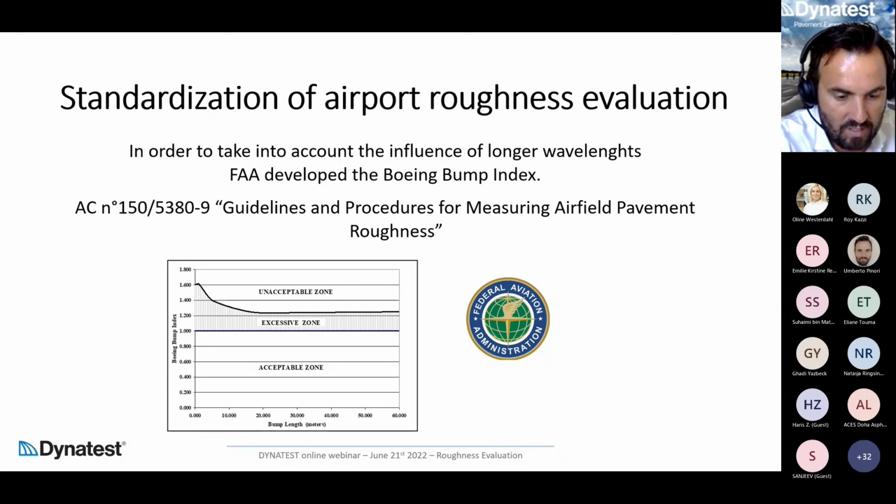For the BBI, how does it correlate to the distance? No, with the BBI, for each single point, we evaluate all the virtual or potential straight edges from 0 to 120 meter of straight edge and report for that point the highest value of deviation. So it's a longer process because for any point, there is a bigger number of straight edges that calculate the deviation. But one value for each single point is reported.